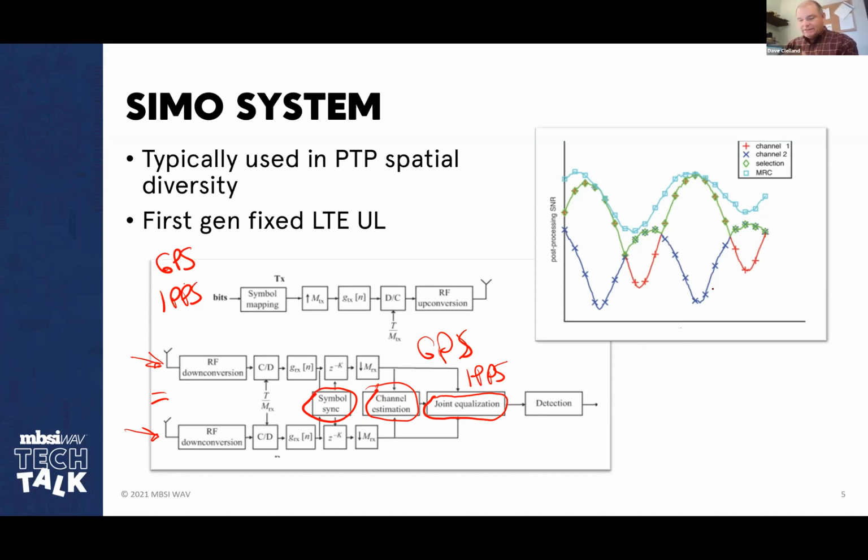In this particular case, this is what receiver number 1 might see here. So the red is going to be receiver number 1. The blue here is receiver number 2, and the equalizer in the MRC is going to mix these together so that the sum is going to be this blue. So rather than having a really deep fade that would go from let's say here to here, maybe 30 dB, something like that, quite severe, MRC will reduce that fade to, let's go here, it might be only 15 dB. I'll show you a graph in a minute that explains this.